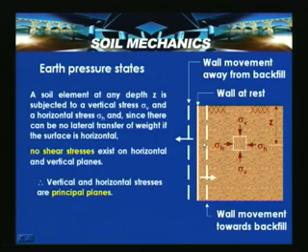In the earth pressure states, now consider wall movement away from the backfill; the conditions are the same as what we discussed earlier. Now, consider an element here at a depth z, which has vertical stress sigma v and horizontal stress sigma h. These surfaces being horizontal, these stresses can be called principal stresses, and if sigma v happens to be the major, then it is called the major principal stress,